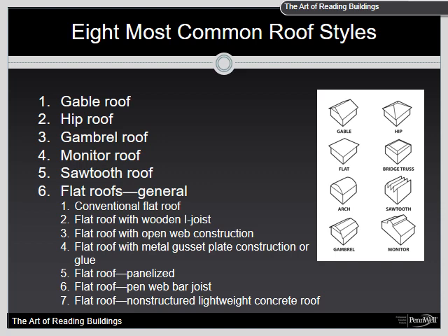In some cases, it is not unusual to find the lower portion constructed of substantial structural members and the raised center section constructed of lightweight material. The shed and gable roofs can either be conventional or lightweight construction. The corrugated metal fiberglass exterior siding will readily fail when exposed to heat and or fire, as will the veneer wood products on these structures.